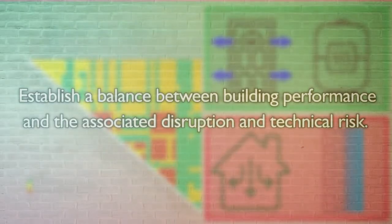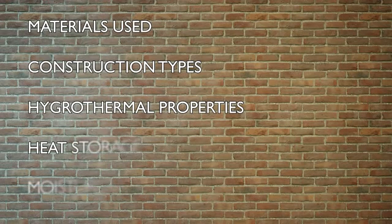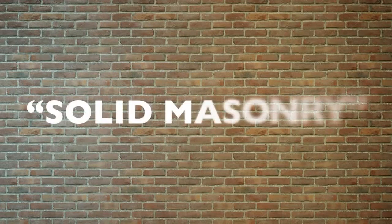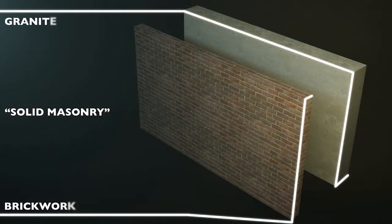The other part of the building assessment is to investigate and develop a thorough understanding of the materials and construction types involved. This is important when it comes to avoiding moisture problems, as the hygrothermal performance of materials and their heat and moisture storage characteristics can have a very significant impact. For example, a solid masonry wall type could be anything from a single thickness brick right through to a foot of solid granite. Both would be masonry, both classed as hard to treat, but very different when it becomes a